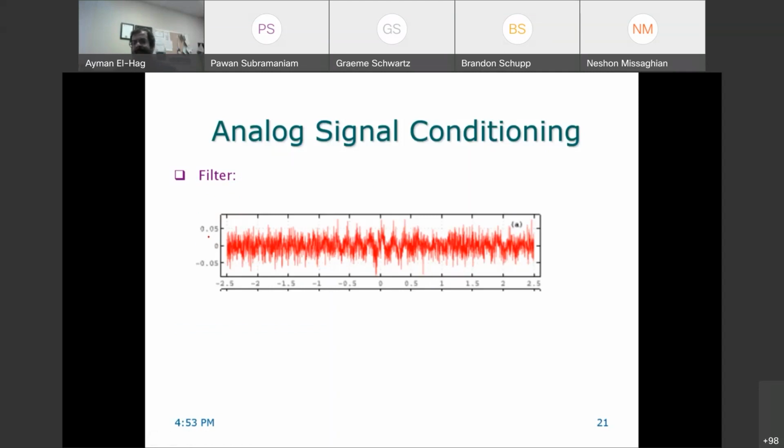This is an actual signal I measured using an acoustic sensor or ultrasonic sensor. This is basically coming from electrical discharges. Okay, so there is an electrical discharge inside a container, and my sensor is at the end of the container, so it's a piezoelectric sensor. Whenever there's an electrical discharge inside, the medium was oil, there will be some waves. These waves will hit the structure. When they hit it, they will generate a very little vibration in the ultrasonic range. Okay, so we measure that.